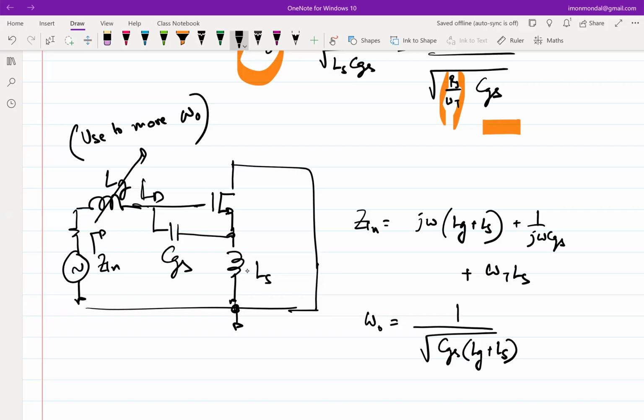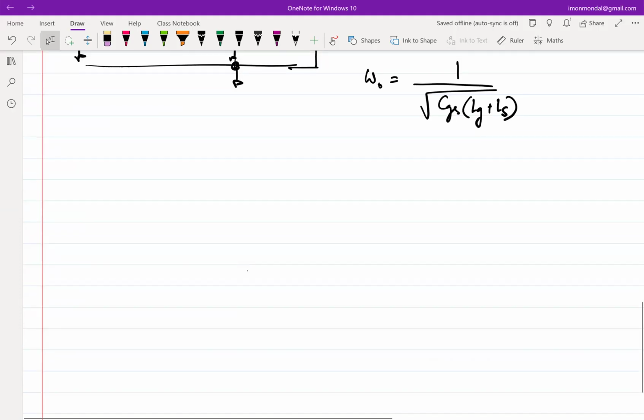But the reason we want to do the LNA is because we want to understand what is the noise figure associated with this. So that should be the next line of analysis. The reason we are doing this is because the assumption was this configuration is going to give you better noise figure than putting an explicit resistor or a common gate configuration. So that's the next thing that we should analyze. Okay, so let's do that.